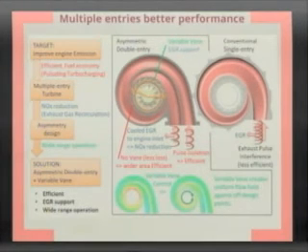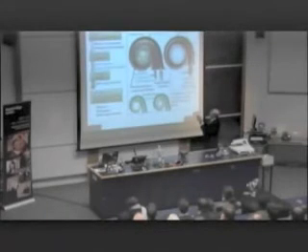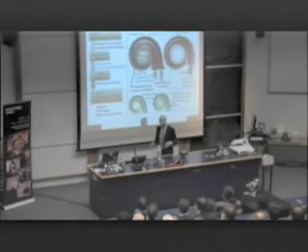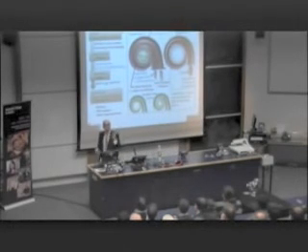Well, we propose to have an asymmetric double-entry turbine. Put two entries, but you have a sector in which you have diminishing flow, increasing EGR. You take away more here. You take nothing here. And therefore, you're capable of re-optimizing this sector on your wheel, and you can do so at different rates of EGR, exhaust gas recirculation. That is another innovation that is tackling unsteady flow performance of turbines at relatively high EGR rates.